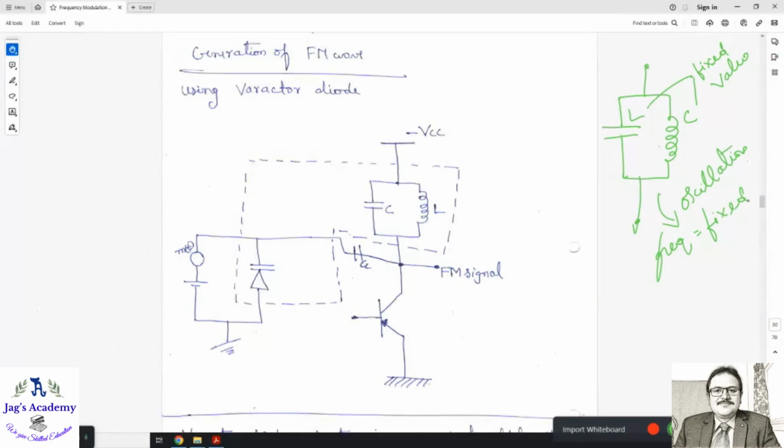I have only L and C, my dear. Where does a resistor come in here? No. Just think. Your frequency will change only because of either the C value or the L value. You can make different frequency oscillations by different values of C and L. Either keep L constant and change C, or keep C constant and change L. Something you need to change.